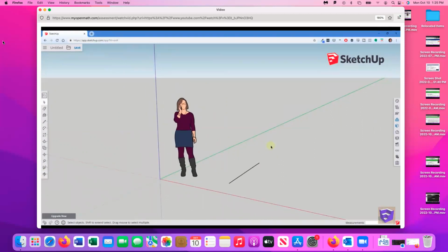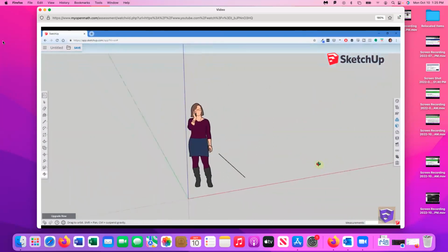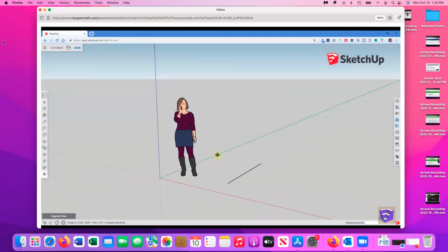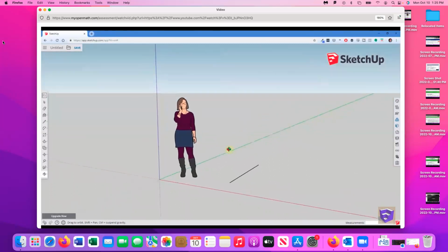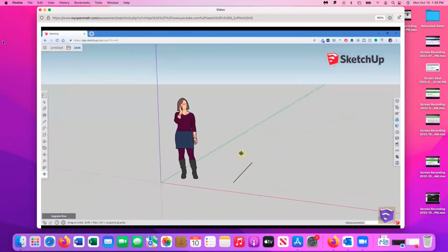And the better way to do that is if you have a 3-button mouse with a scroll wheel, which is going to be really important if you're going to be using SketchUp a lot. You're really going to want to have that 3-button mouse. What you can do instead is you can click and hold your center mouse button in order to orbit. And so what I'm doing is I'm clicking and holding that scroll wheel down. So I'm clicking it like a button, not rolling it and holding that. So that allows me to orbit.